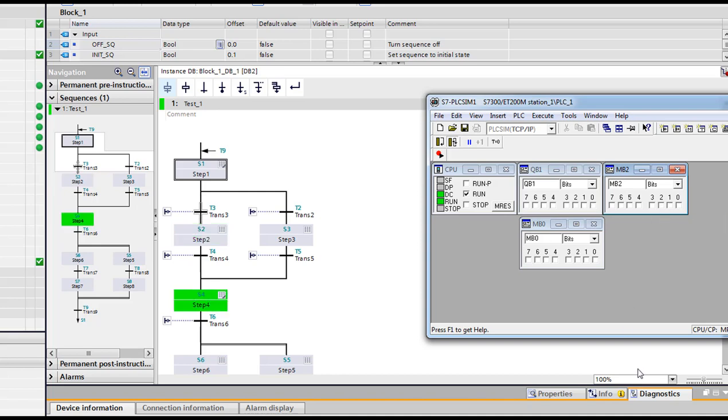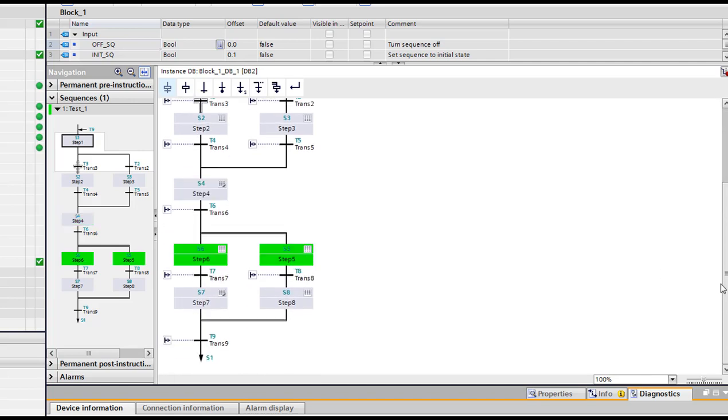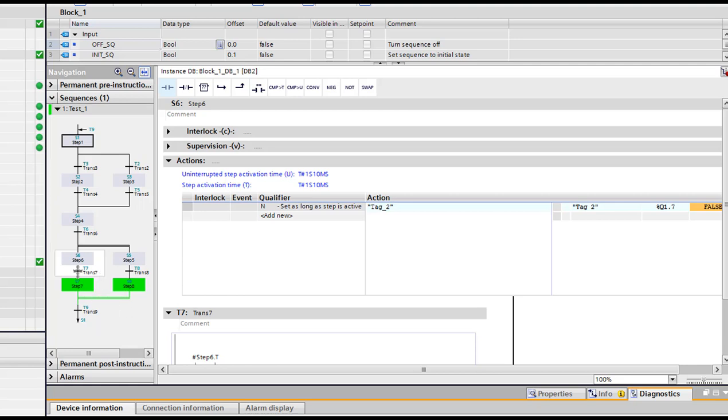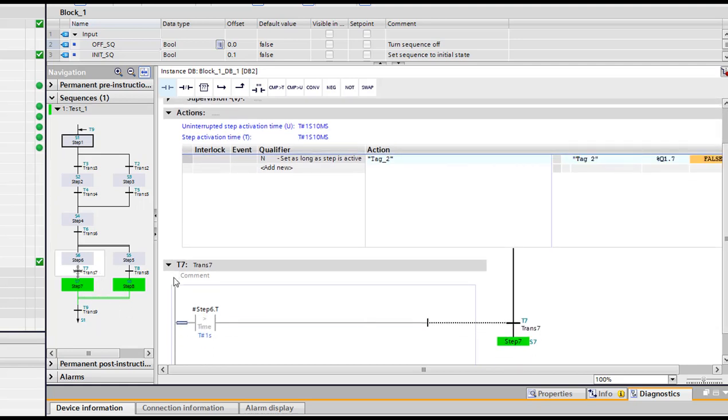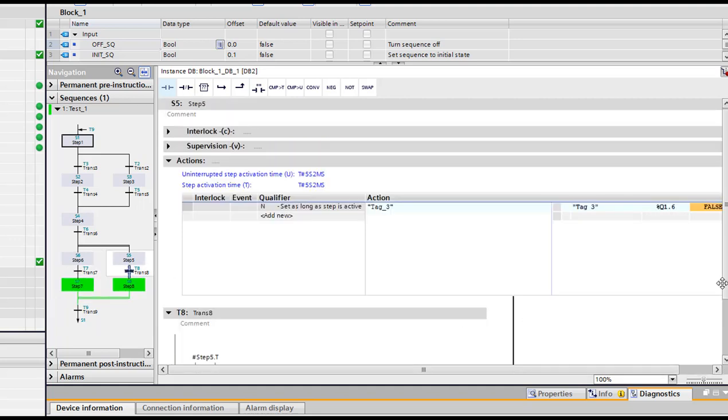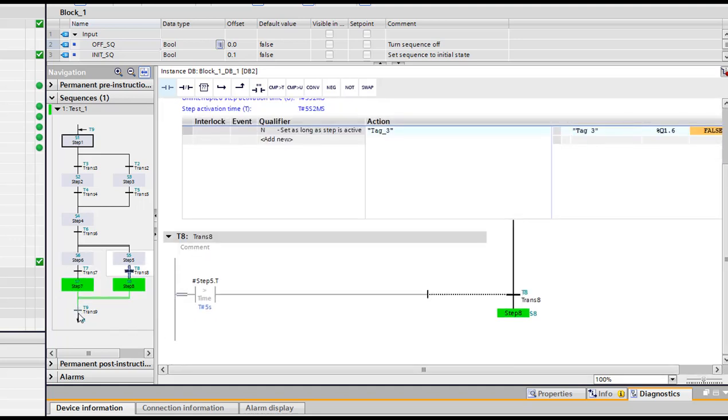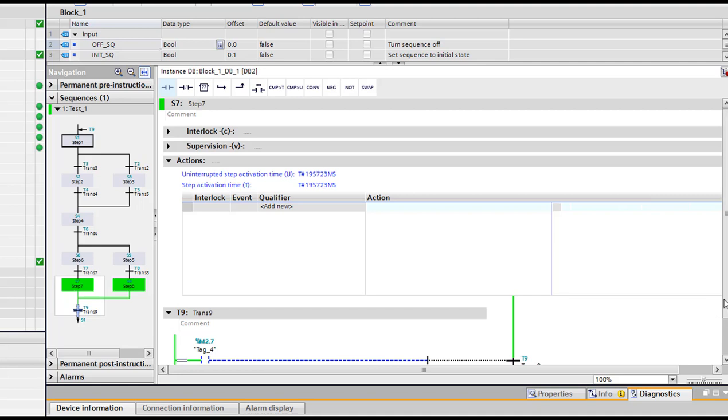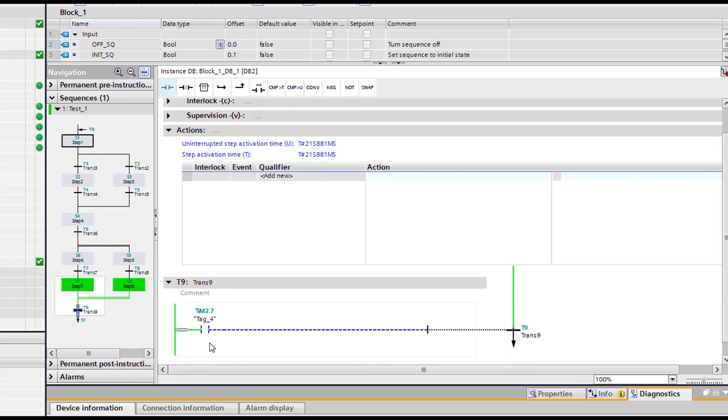Yes. So at 2.2 we have a step, another step, and then as you saw, the two steps are activated here, and here I added some delays. I added them here, this 1 second and this 5 second, and then they wait until these contacts get closed.